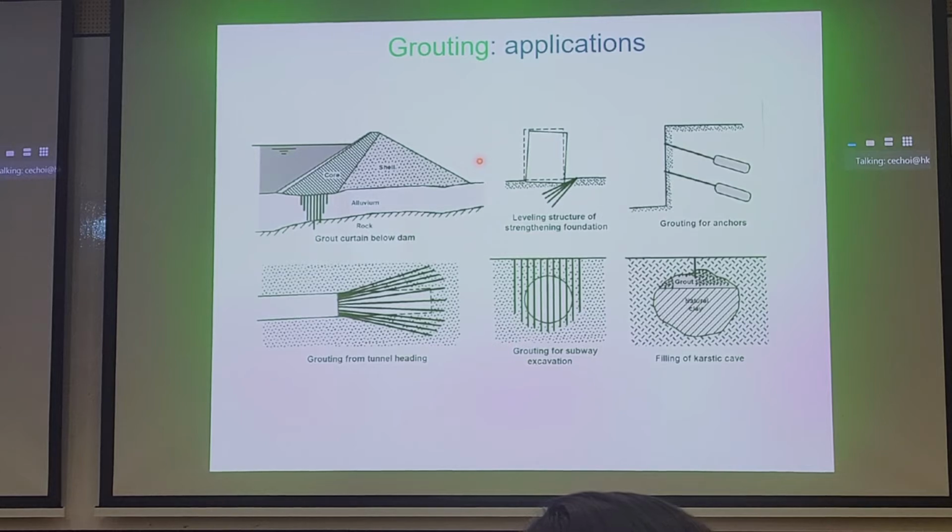In fact, sometimes we install more than one grout curtain. If one grout curtain doesn't work, we try to alter the hydraulic path of the water using perhaps several grout curtains, or even in some circumstances we have 2 sets of sheet pile walls. So that's one very common application of grout use in Hong Kong. Anytime you have a cofferdam right beside the sea and you need to excavate inside the cofferdam, we often leverage grout curtains.